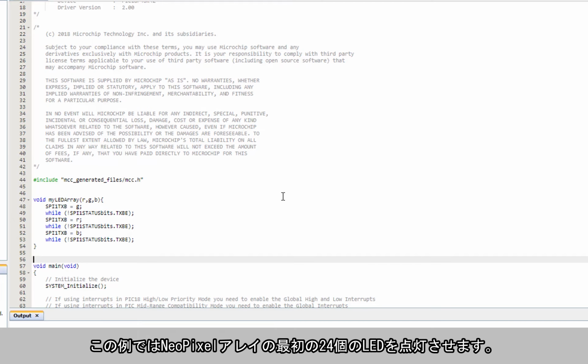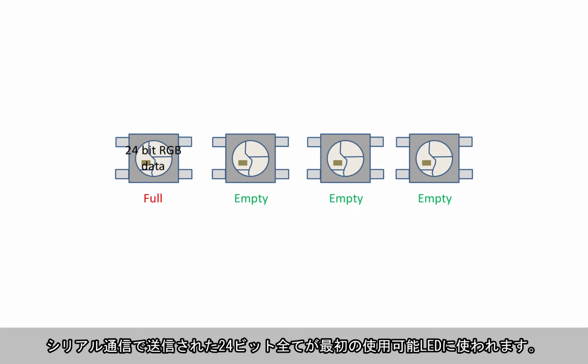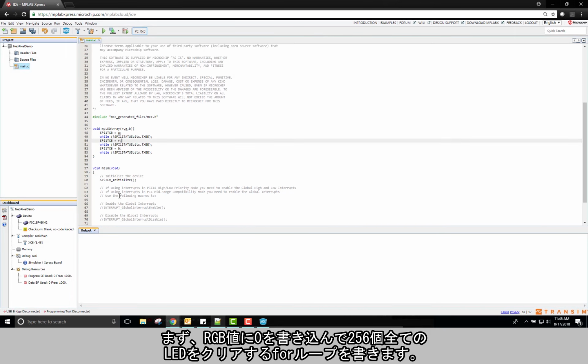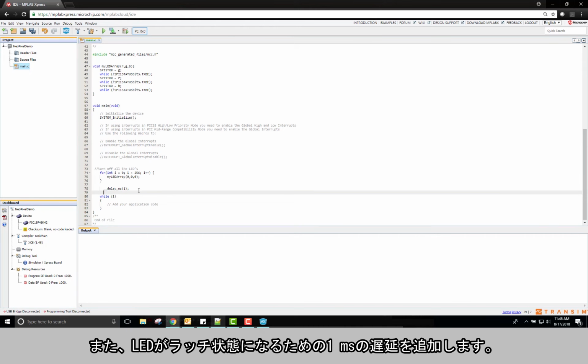For this example, we will light the first 24 LEDs of the Neopixel array. The Neopixels are wired in series. Every 24 bits sent over the serial communication is used by the first available LED. If the LED has already been written to, then the data is passed on until it reaches an available LED. I will first write a for loop to clear all 256 LEDs by writing zeros to the RGB values. I will also add a 1 millisecond delay to allow the LEDs to reach their latch state.